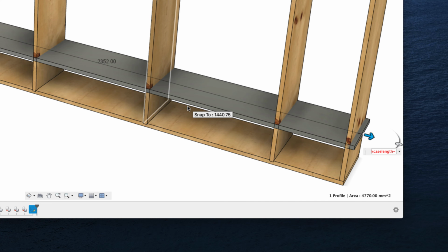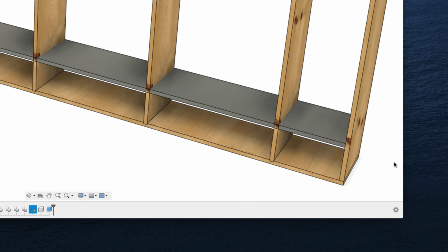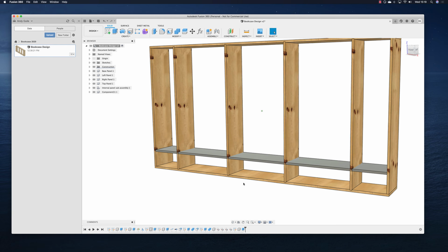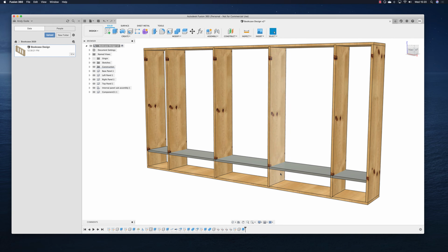So rather than typing minus stock thickness, I can now type in here minus open brackets stock thickness times 2 close brackets. So you can actually start to do some quite complicated formulas, or expressions as they're called, inside Fusion. So I've now got a shelf all the way across here. The problem is, of course, that's just one big solid piece of wood.